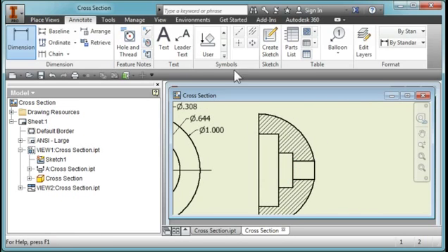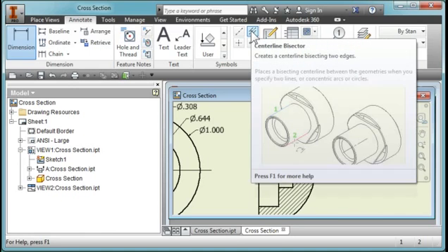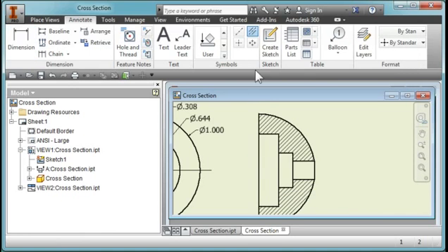Before I do that, I'm going to add a center line. Go back to View. I'm going to select this center line bisector tool. When I point to this line, I'll try to grab the center of the line, and when I do, it'll be highlighted with a green dot. I'll select that. Do the same on this side, grab the green dot. You notice now I get a center line. I'm going to hit Escape, that was with my right mouse button, and then I'm just going to extend these lines out a bit.